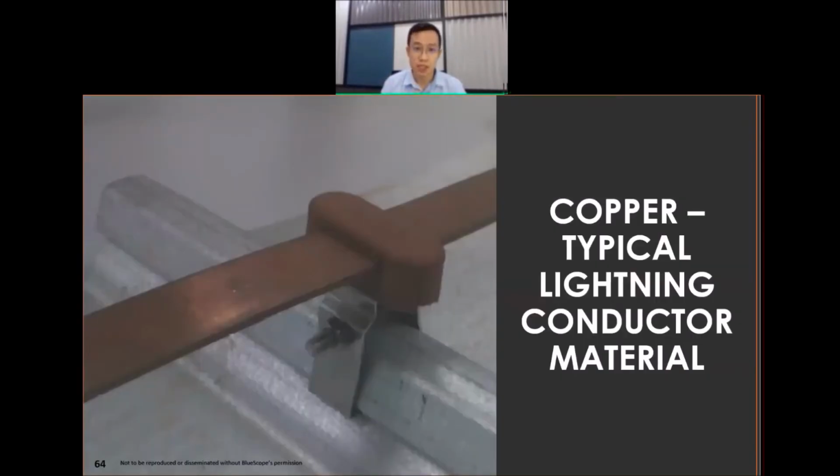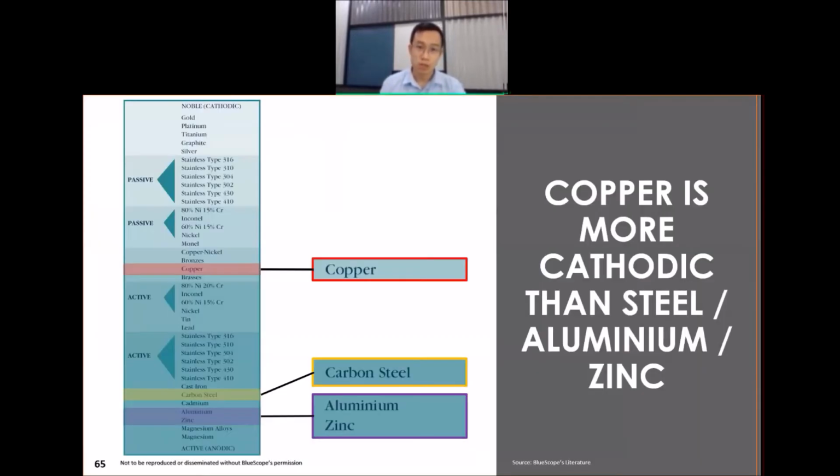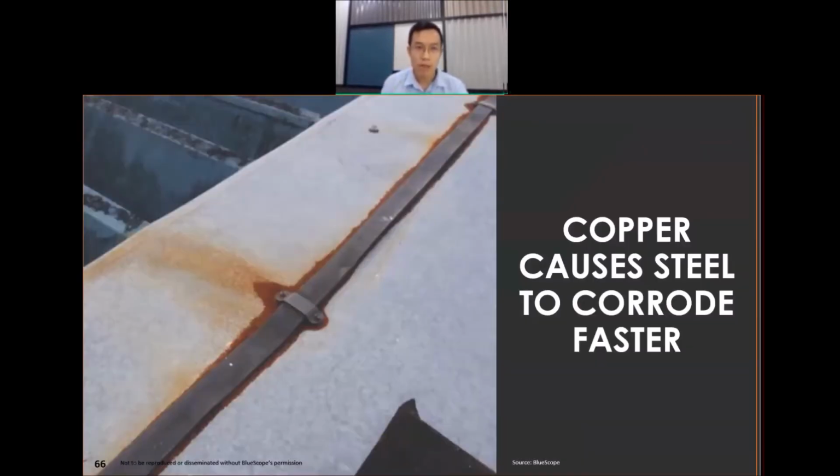but in terms of lightning conductor material itself, the typical material used is always copper, because I believe most of you will know, copper acts as a really good electrical conductor. However, if we look back at this Galvanic series, copper is more cathodic, also called more noble, compared to steel or even aluminium and zinc. Because of this, copper will cause the steel cladding to corrode faster. Meaning, if you install a copper lightning arrestor resting on, for example, steel cladding or steel flashing, it will cause the coating, which is typically made of zinc or zinc aluminium, to react faster. And in no time, you'll see signs like rusting around the copper tape.